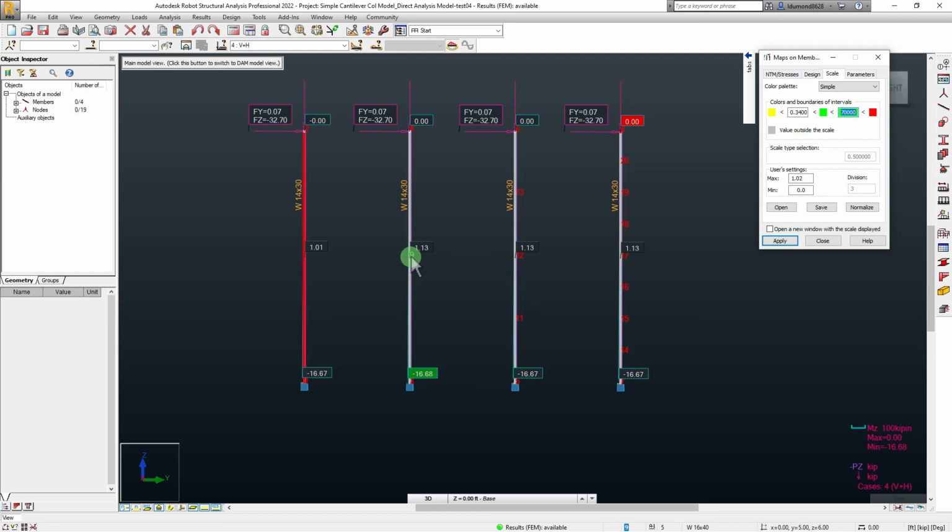The reason why this is gray is because anything that was above 0.7 is set as gray. So let's set it at anything above 1.0, hit apply. Oh, if it's outside that scale value, it's still gray. So let me demonstrate so you don't think I don't know what I'm doing. I want to modify this. I have it as 1.5 now. They're going to turn green.